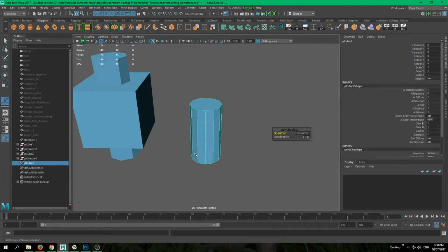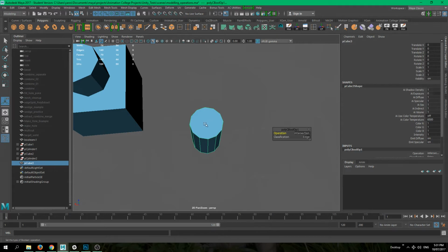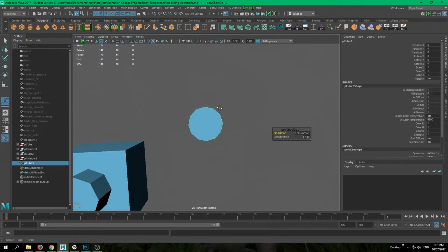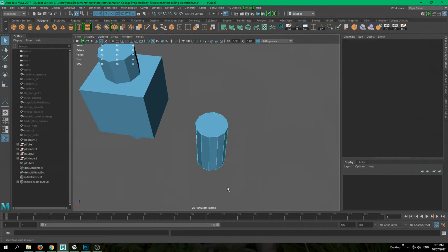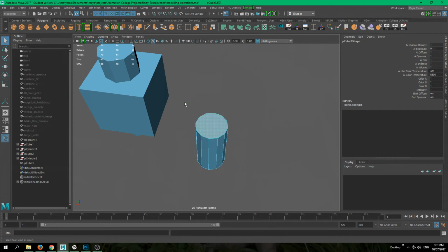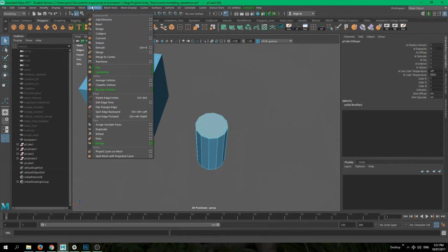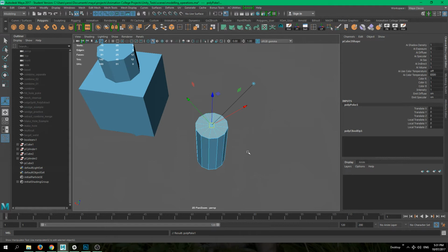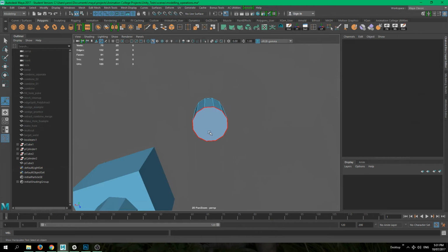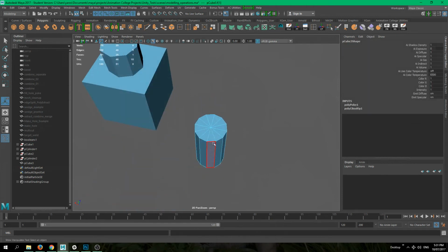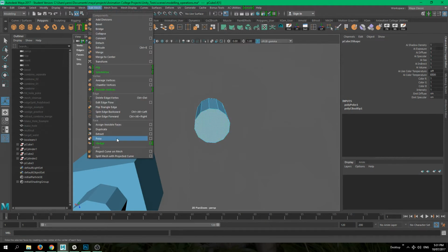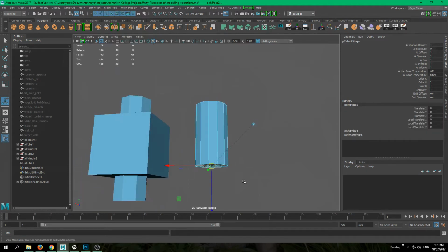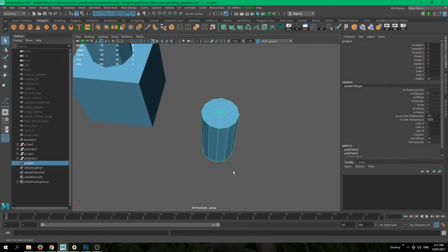And the only thing you would have to do with this one is to make sure that you connect those elements together properly. There is a really easy way of doing this. You can select the face and go under Mesh and Poke. So this usually works only for those types of scenarios where you have a cylinder and you have this huge n-gon and you just want to create edges going inside. So again, under Edit Mesh you can find this Poke. Now your cylinder is properly fixed.